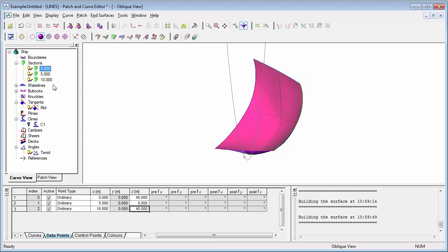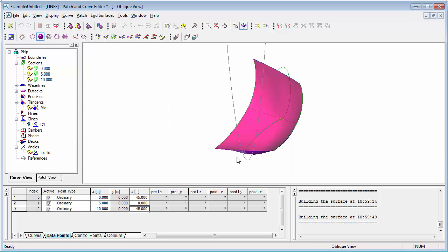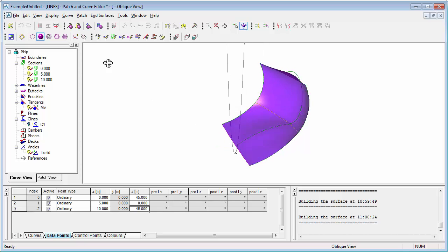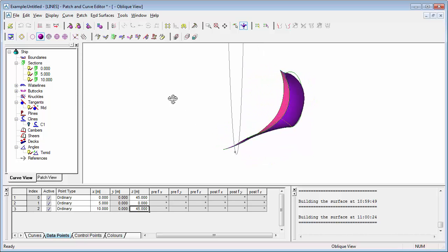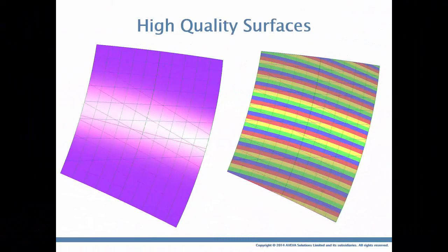This type of feature is very useful for controlling the tangency of a hull surface, say for example leaving the flatter bottom or leaving the keel. It's much easier to do it this way and get a smooth result than manipulating control points of a surface.